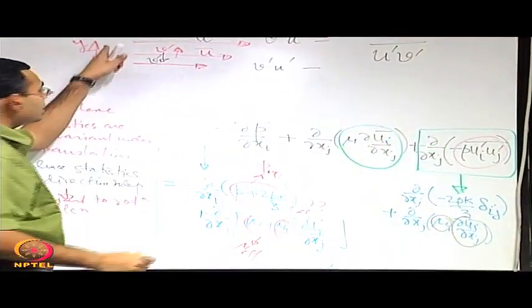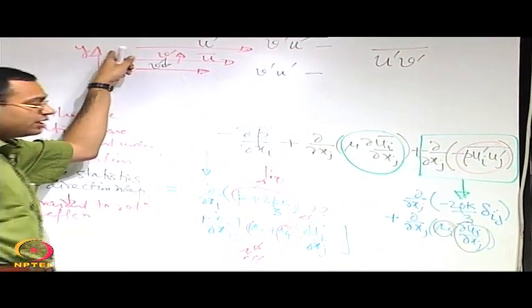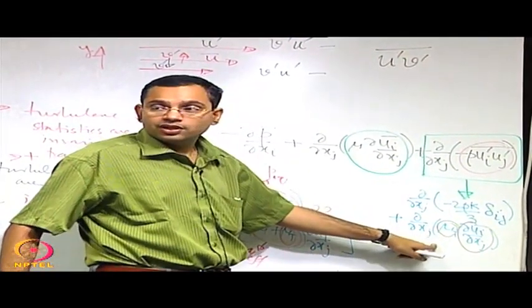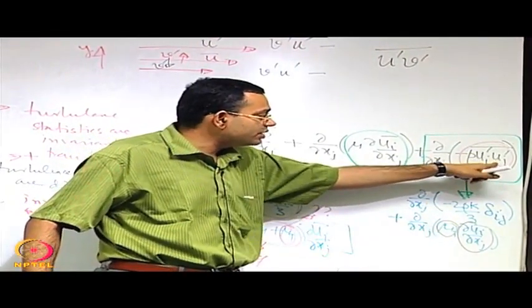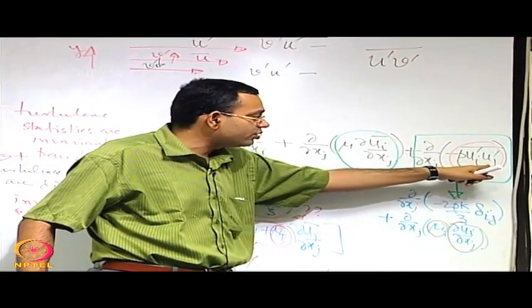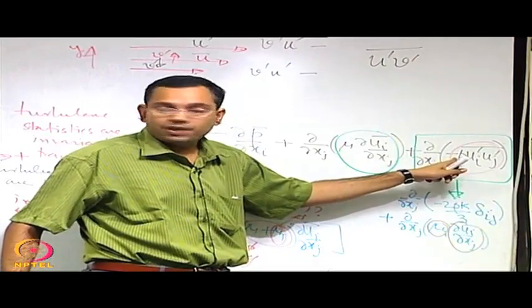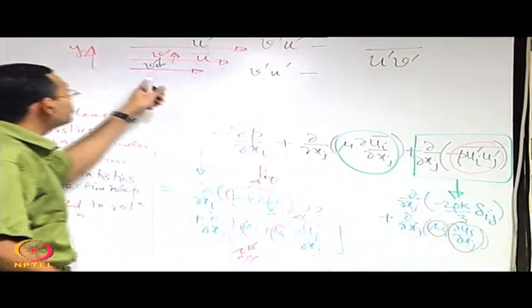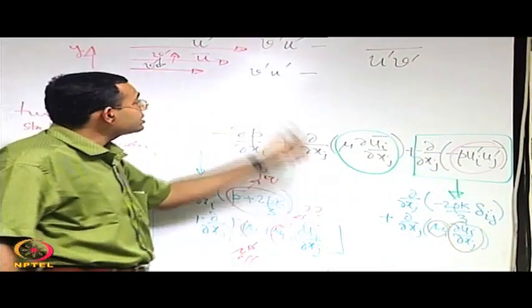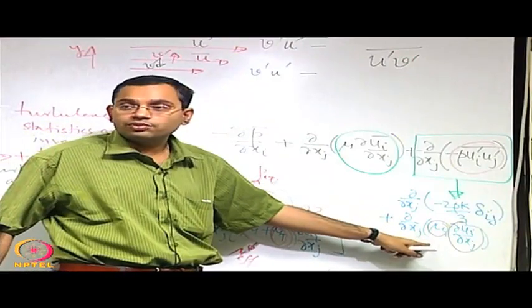Here the velocity gradient along y is positive and therefore mu t has to be positive, because ui prime uj prime averaged when i not equal to j is itself negative, and that negative with the minus becomes plus. Here del u del y in an average sense is positive and therefore mu t has to be positive.